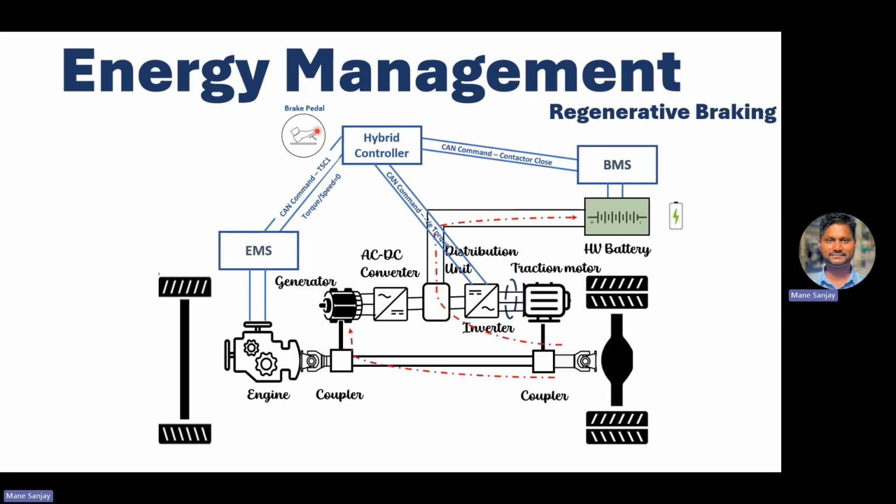Because just imagine you are applying your mechanical braking. At the same time, you are applying this command to operate the motor to work as a brake or kind of braking effect. So in that case, what will happen if the driver is expecting, say, 50% braking pedal? If the driver wanted to stop the vehicle steadily, and you are sending the command as well as your engine is adding the braking effect, then from the 50% you will experience panic braking.